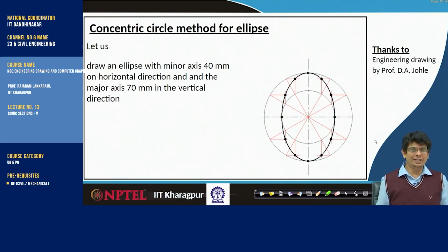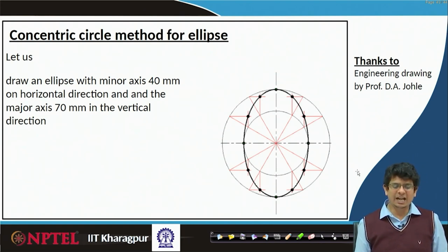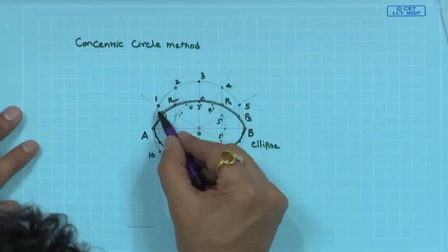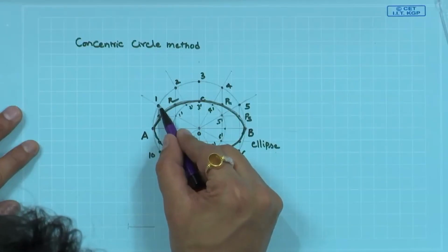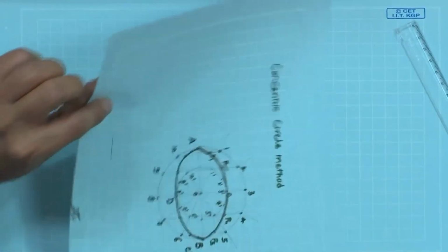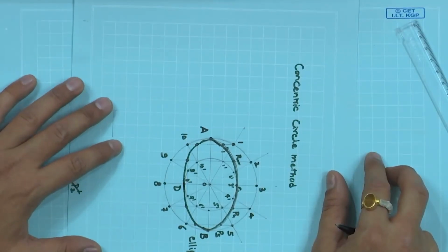So, we are done with the horizontal kind of ellipse. If we would like to construct a vertical ellipse, that means the major axis is aligned with the vertical axis, the same procedure we have to do. Instead of dropping this one line all the way down, we are going to project this one line onto the horizontal axis. By symmetry, it turns out to be this kind of circle. Please practice this example.